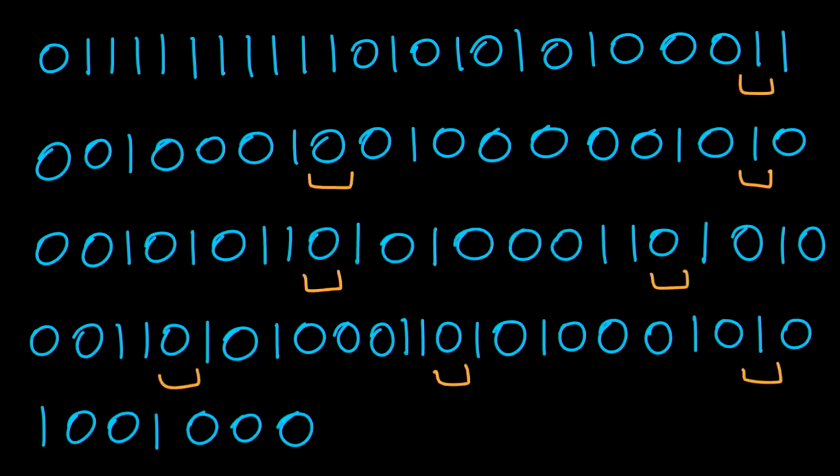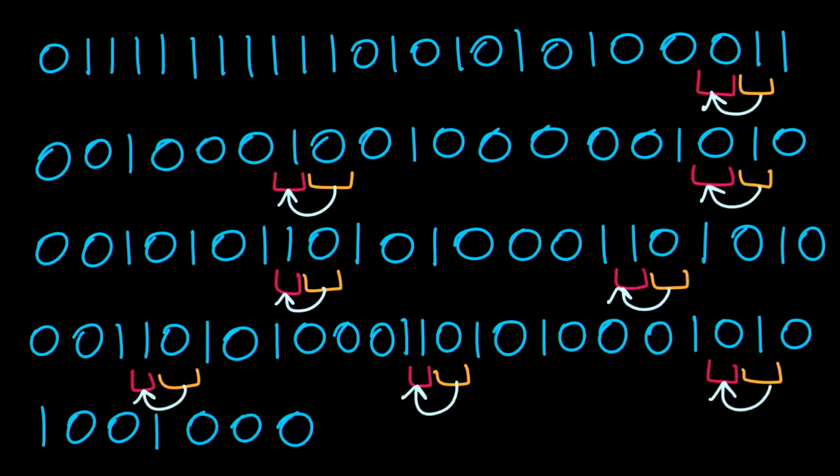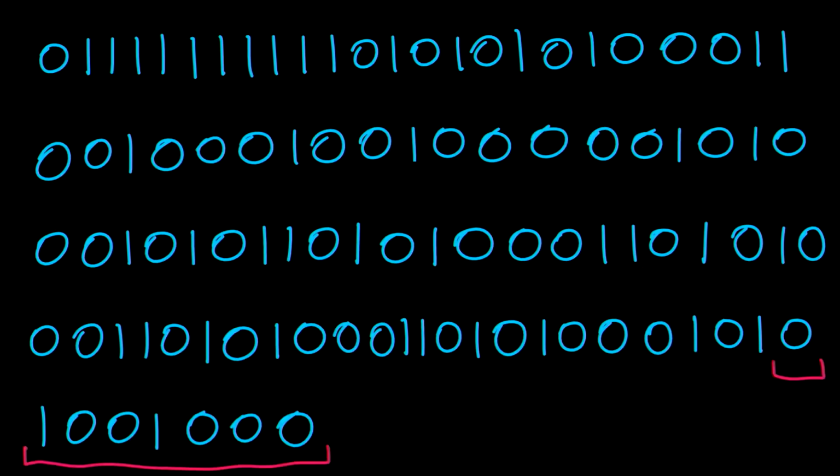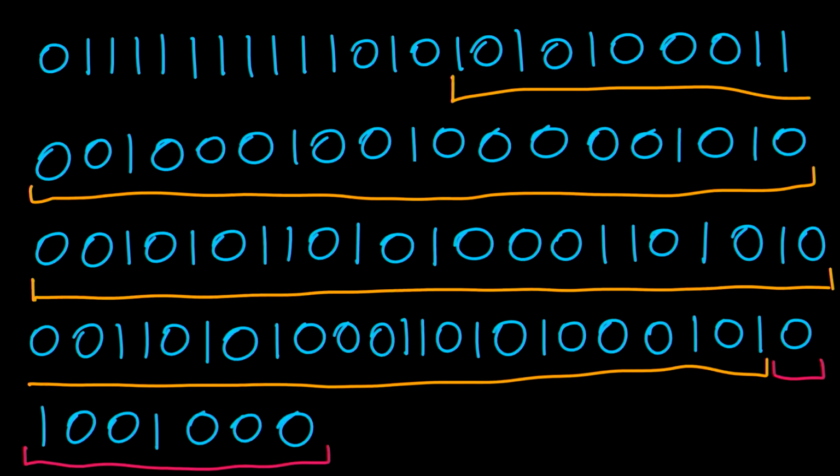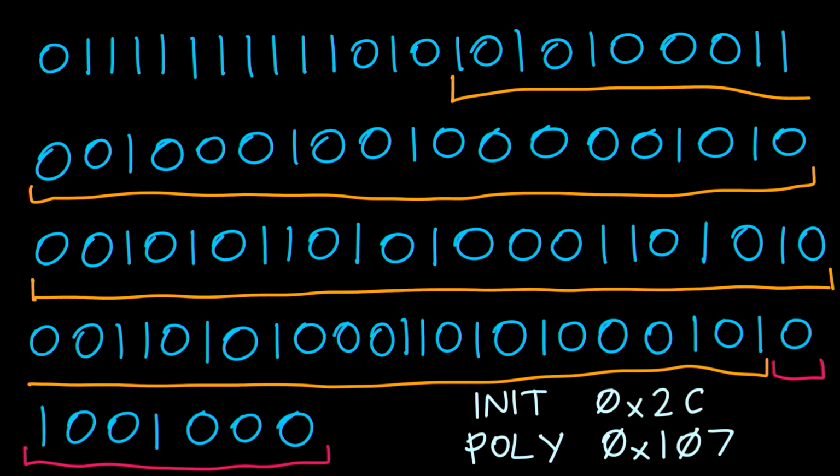After a bit of head banging, not the metal kind, more like head desk banging, you see that every 9th-ish bit is the opposite of its previous bit. Here you can see, if the previous bit was 0, then the next is 1, and if 1, then 0. So there's some kind of parity padding bit. It's not really parity because it's only parity over the last bit, but it's definitely doing a good job of padding it out. And then we can eventually see that the last 8 bits are actually a CRC of all the data excluding that prefix.